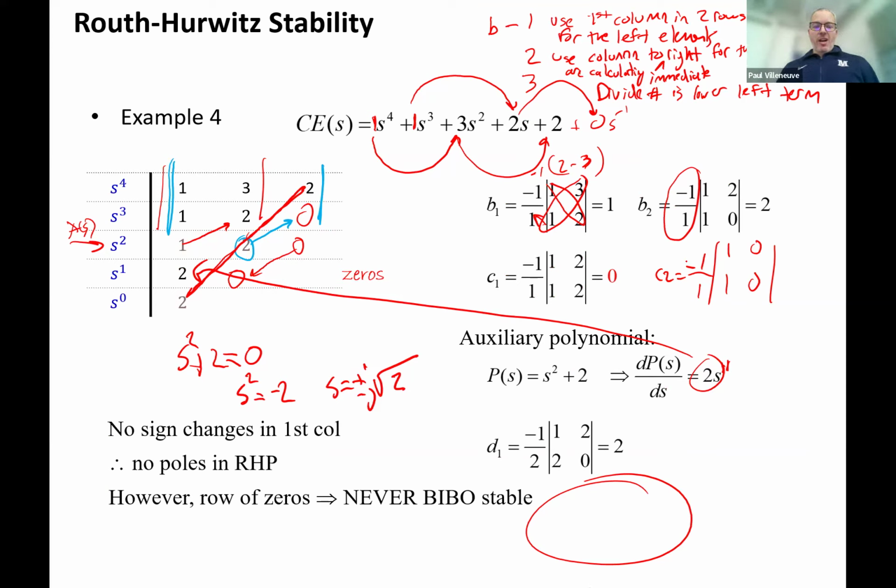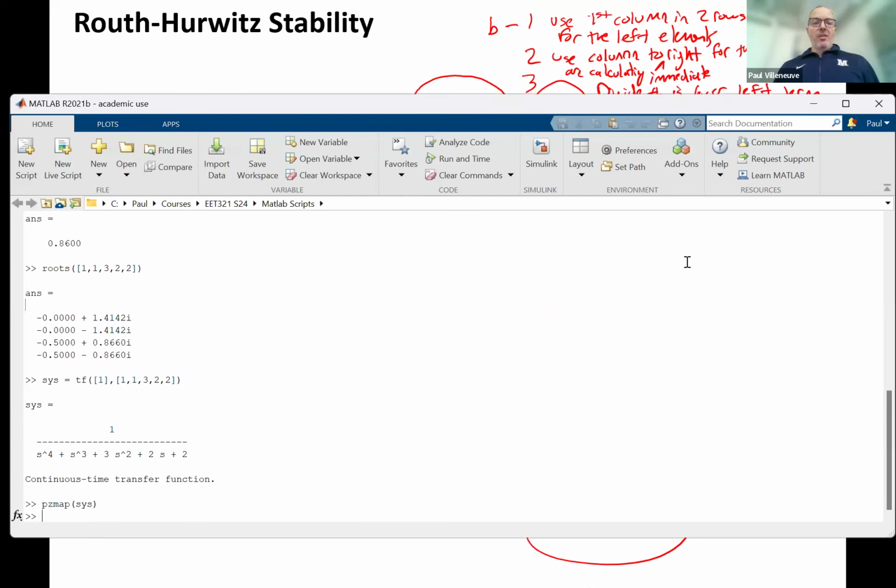So the question is, why did I put it in MATLAB with a 1 over here? Because my transfer function has to have a numerator and a denominator. If I have a numerator of 0, what is something times 0 going to be equal to? It's always going to be 0. So if I have a transfer function with a 0 in the numerator, no matter what input I provide, the output is always going to be 0. So I'd get no results.